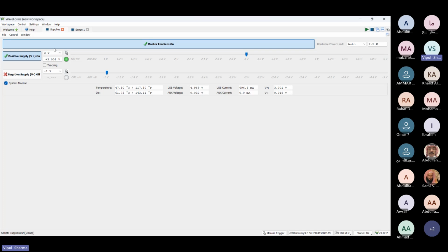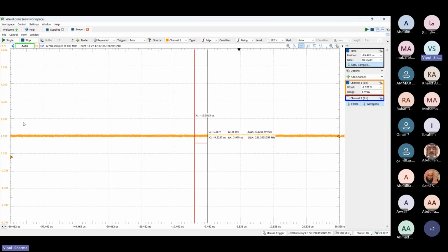And so from the bandgap reference also, we generally expect that if 5 volt is my ideal VDD voltage to be given to that circuit, then plus minus 10% means 4.5 to 5.5 volt. Within that range, this circuit should remain constant, like the output voltage should not vary. So this is what I think this circuit is performing. Basically this is what I wanted to show you, how a bandgap reference circuit is working and what needs to be checked here.